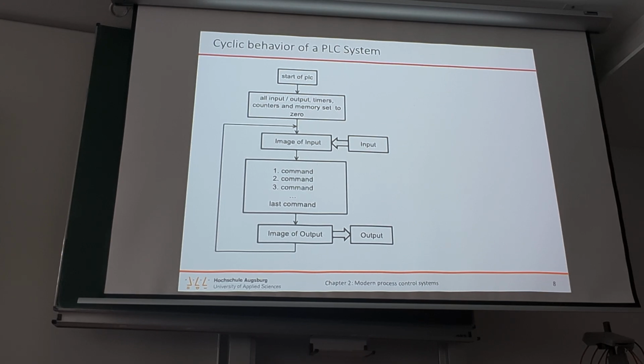And if I would do a project now, I would use a structured text program. But most of the PLCs by now can actually run external code fragments as well, like C or C++ code, with some restrictions regarding real-time capabilities, but they can do it. Even Python code can do it.